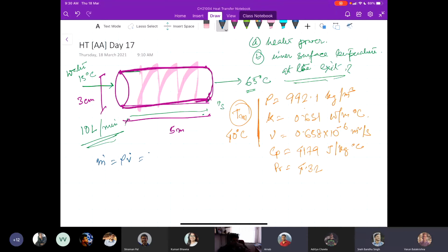I've calculated the final value. No, without calculating m dot, how can you put it in Cp delta T? I have calculated the whole expression. Finally, it is like 0.16535. I missed the point. It is coming around 0.165 kg per second. So Shraman, check your decimal. Yeah, I missed a 0.1 for the density.